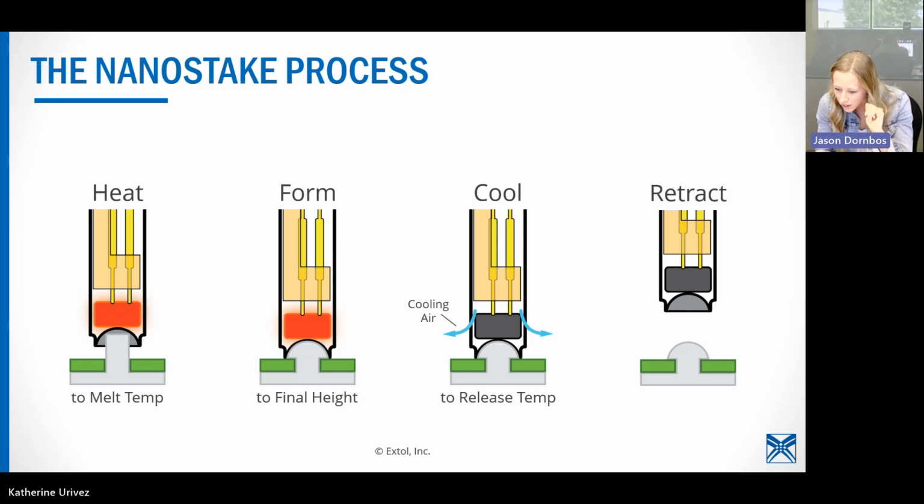And then, this is an interesting question. Given nanoSTAKE applications typically require or have smaller bosses, how many stakes do you need to compensate, as opposed to InfraSTAKE, to get similar strength out of the two? Sean's going to go a bit into the strength calculation as well, but we have a general rule of thumb for calculating what stake strength is going to be. With nanoSTAKE, there's a slightly higher safety factor than with InfraSTAKE. So you probably do the math, figure out how many stakes you need to compensate for one traditional InfraSTAKE point.